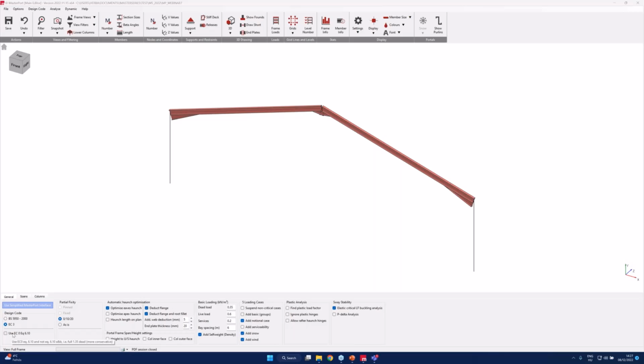You can change this by clicking the checkbox, so it uses 6.10 instead, should you wish. We are going to pin our bases for design, but for in-plane stability and service loading cases, we will use 10% and 20% base fixities.